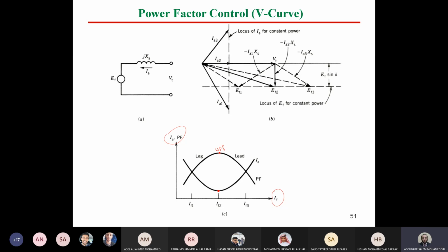If we have a machine of 5 kVA and we have a mechanical load of 3 kilowatt, if we neglect the machine losses, this 5 kVA guys is the rated value, and the machine now is working at 3 kilowatts, and if the power factor is unity, what is the maximum reactive power that we can achieve without overloading the machine?